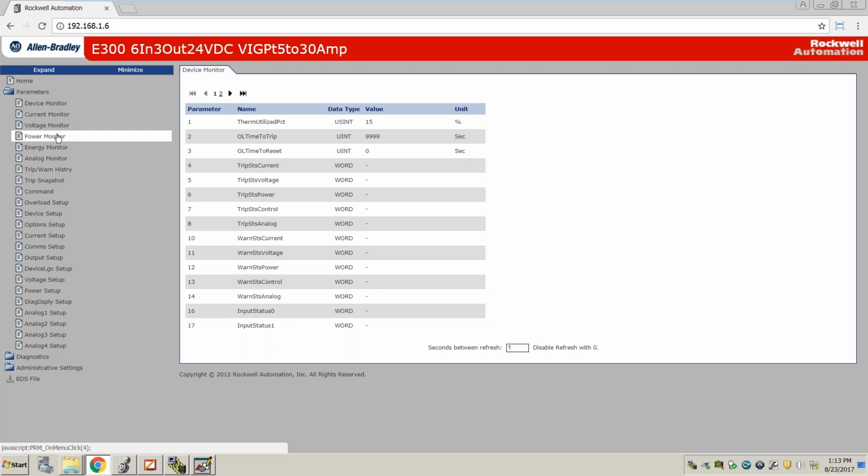And what is really nice here is you have a time to trip. What this does is it gives you some predictive maintenance. So say that time to trip starts decreasing rapidly. There you go. The overload trip.